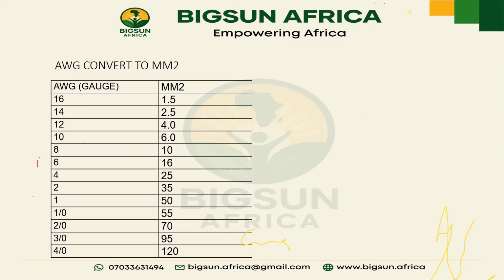I can also add, when you check out that formula, I is equal to V over R. Exactly. So that is the one we should be using now. I is equal to V over R. Now, we've gotten the two resistances, just like we calculated. The first one is 18.84, right? Our first R, when we connect it in series. And when we connect it in parallel, our resistance is 0.774, right?